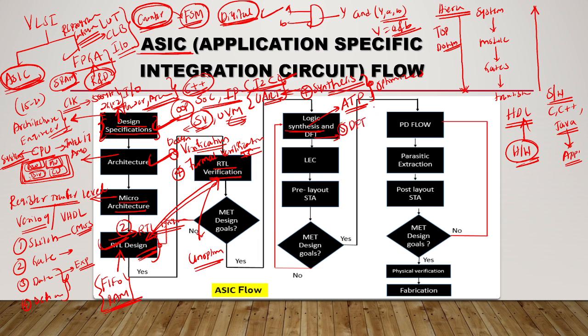Then you have DFT engineers also. DFT is nothing but design for testability. Design for testability means they will test whether your design is meeting the specifications or not. They will use some scan tests and built-in self test. Some techniques they will use and they will test your design. And LEC is nothing but logic equivalency check.